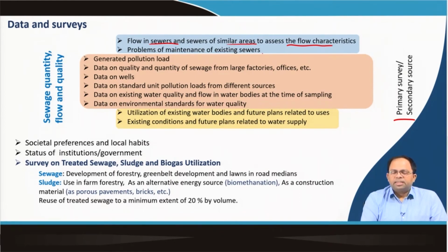Problems of maintenance of existing sewers, that means we need to survey and see where the choke points are, where people have thrown garbage and it is blocked, and if it is being maintained and so on. Then total pollution load, that is total sewage generated, what is the BOD of that sewage, and accordingly what is the pollution load. Then data on quality and quantity of sewage from large factories, offices, data on wells,